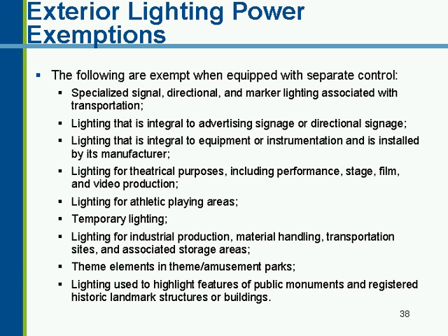There are also exemptions, as we mentioned, to the exterior lighting power. A lot of these you'll see are similar to the interior exemptions, but there are a few different ones. The first one, specialized signal, directional, and marker lighting. This is typically found in exterior applications. That can be exempted as well. Lighting integral to advertising signage. Again, it's a part of the sign. It comes from the manufacturer. It's exempted. Also, lighting integral to equipment is exempted.